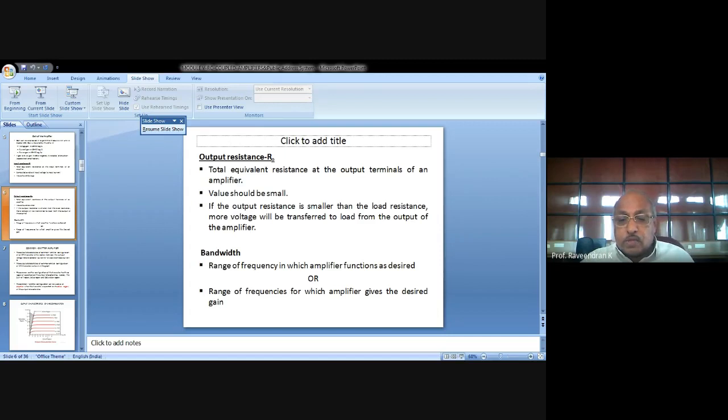Since the transistor is biased to operate in the active region, this signal is amplified beta times larger than the input current in the common emitter configuration. Very similar to what we have seen. Hence, the collector current also varies sinusoidally about its quiescent value. Thus, the output voltage varies sinusoidally. The output voltage will always be an inverted amplified version of the input voltage.